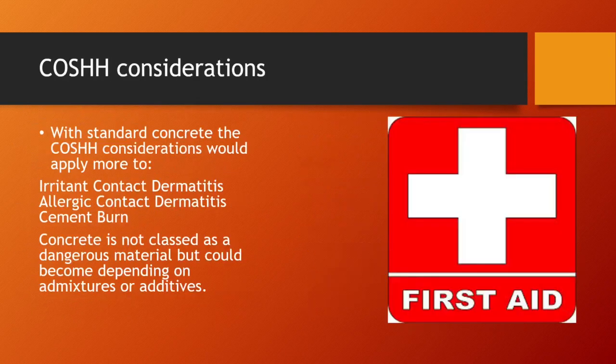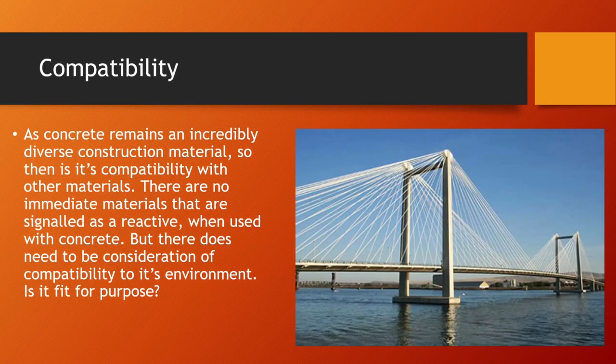So I did mention earlier about the gloves, the goggles, protective boots, Wellingtons for when you're working with concrete. There's a lot of chemicals involved. You've got your cement burn. If you was to get it in your eyes, it's not going to be good. It really isn't. It's a really, really difficult material to work with if you don't observe the safety that comes with concrete. It looks very innocent. It can be really, really dangerous, very dangerous.